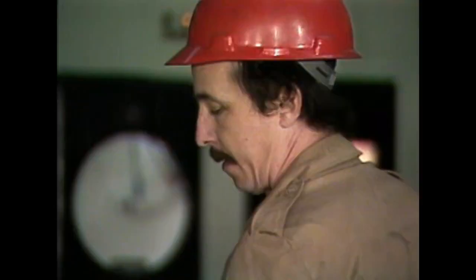There is a relationship between steam flow through the turbine and the demand for electric power on the power generation system. This relationship is helpful in understanding why steam flow has to be controlled. Basically, if more power must be generated to meet an increase in demand, steam flow must be increased to cause the turbine to work harder to turn the generator. On the other hand, if less power is required, steam flow must be decreased.